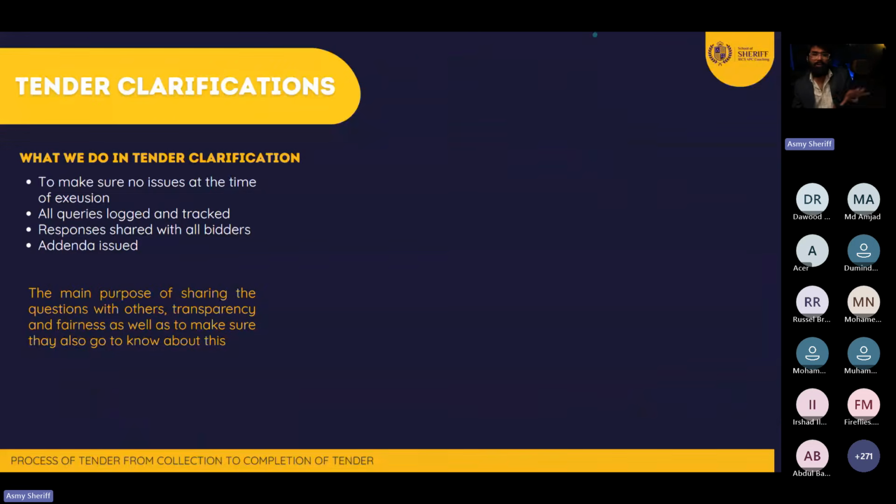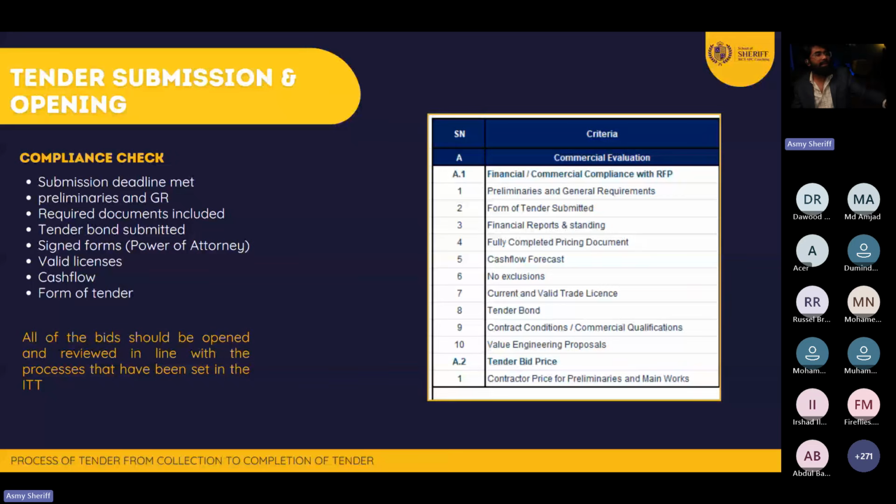Right. So when we speak about that, after you receive the tender clarification, it's not going to be one question, guys. There will be many questions. They will come back to you. Every day you will receive questions. But you as a main contractor, or a subcontractor who is dealing with the tender, or maybe a consultant, you're going to collect them. And every week maybe, or every 2 weeks, you're going to answer almost 100 questions, 200 questions and send that back to them. It doesn't mean that once you receive one, you immediately answer and send it back. No. So you will collect.